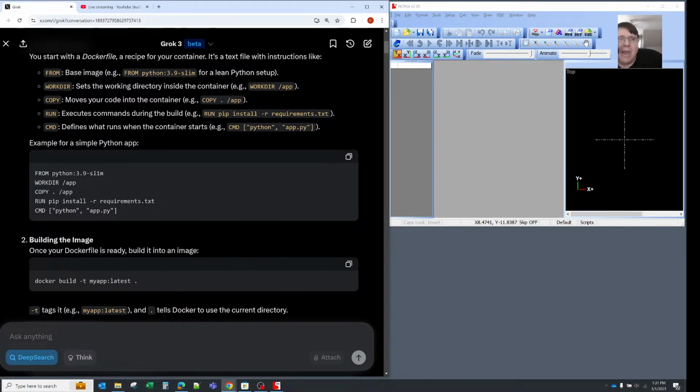This is tying back, Ron, with the question that you asked, I would like it to analyze the solid models. What you want to do is have it help you write a tool. That tool can be Python. That's probably the easiest one to get started with, or any other scripting language of your choice. You want to develop a lightweight standalone app that you can launch. You can feed it a file, or a folder with a group of files inside, and have it iterate through the collection, check each one, and report on it.